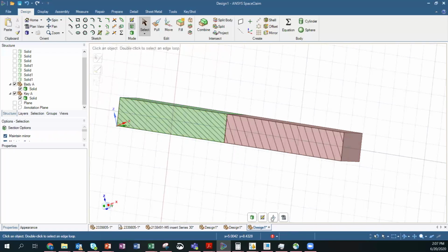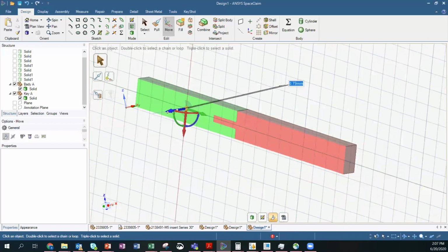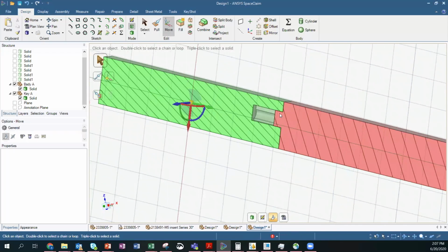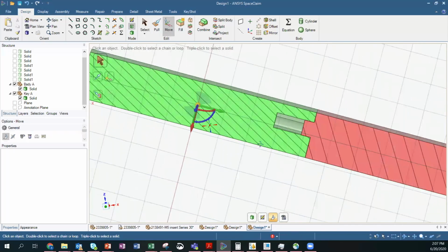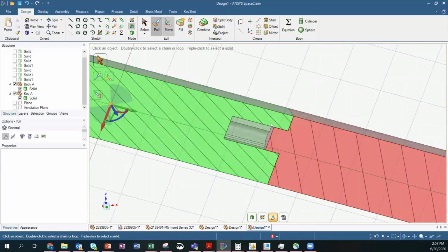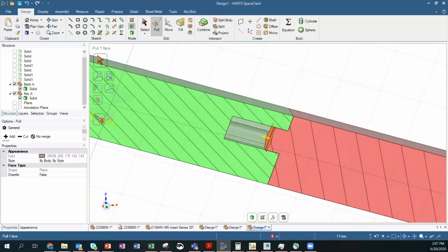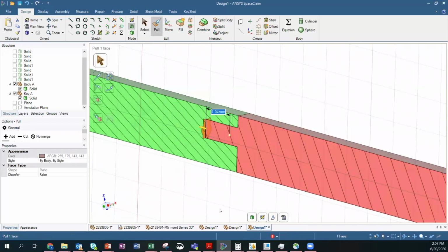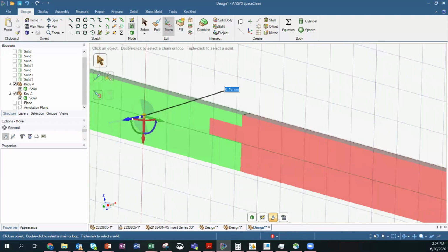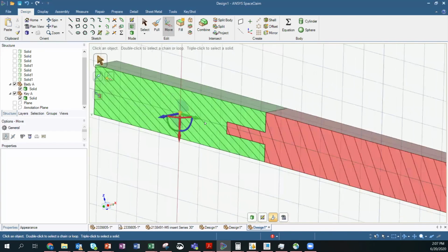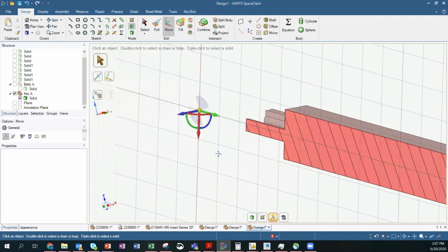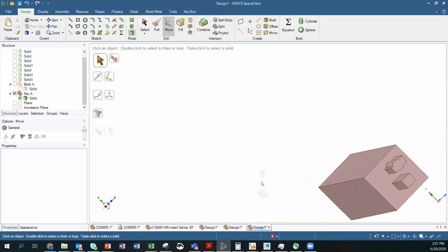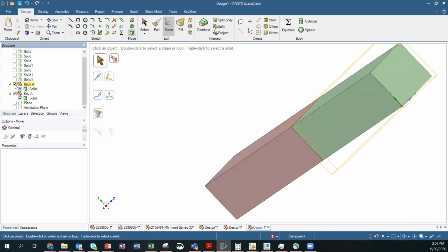So when you do a cross section, you can see how the keying happens. You can see the key is happening right here. They're meeting with each other. This is the key function. So if you suddenly decide, hey, I want to do this, just go to pull, click on the up to, click on the surface, it's done. And again, you can see the cross section, how they are functioning. And if you just want to see the key A, just hide the body A. You can see key A, how it does. This is the key A. This is a key that goes inside the other body.